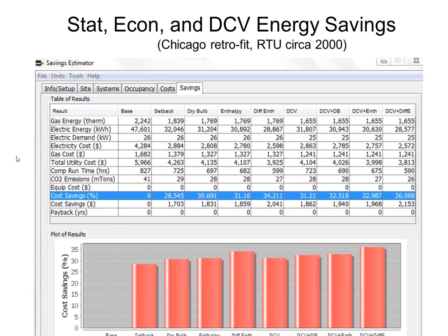And like I said, I've replaced 8 out of several thousand. Now there's probably another several thousand that I've never personally gone back and tested, so I don't know about those. But even if you say the 8 is 50 instead of 8, it's still a pretty low rate. So I would just say you check them every couple years. If it's an industrial application and you're manufacturing stuff that's off-gassing CO2, that's different. Use a different grade of sensor. You calibrate those differently.